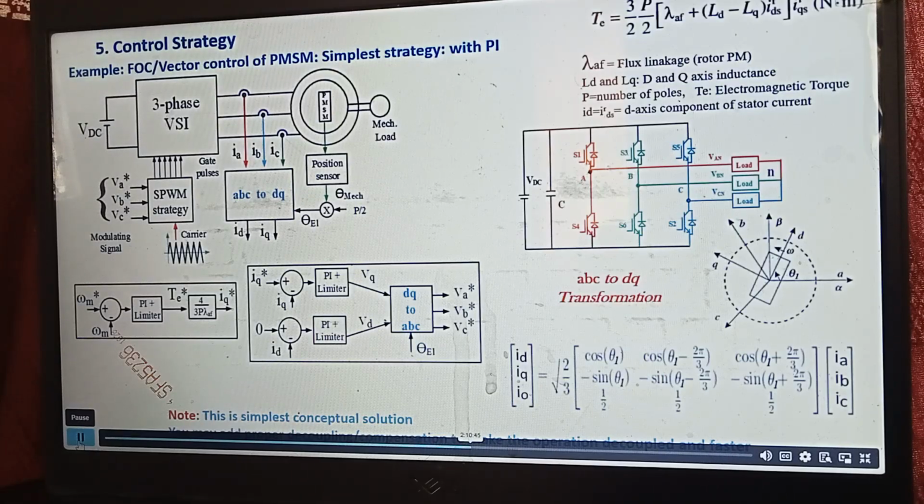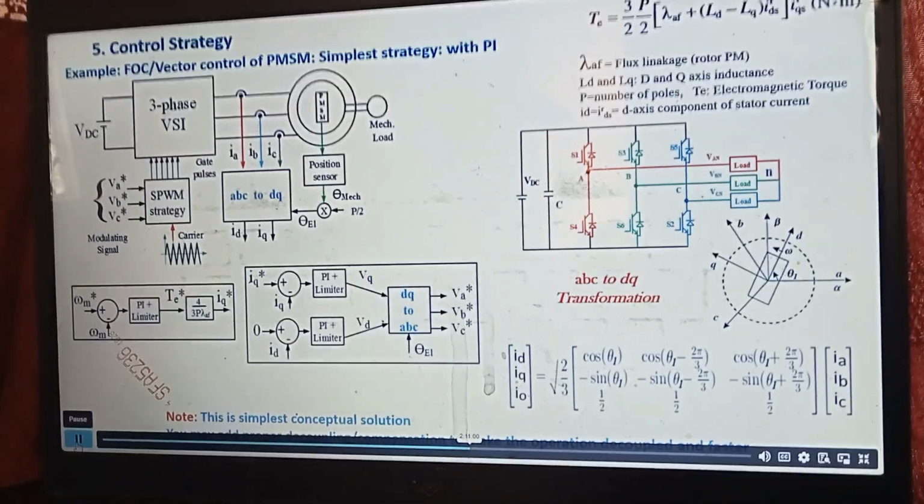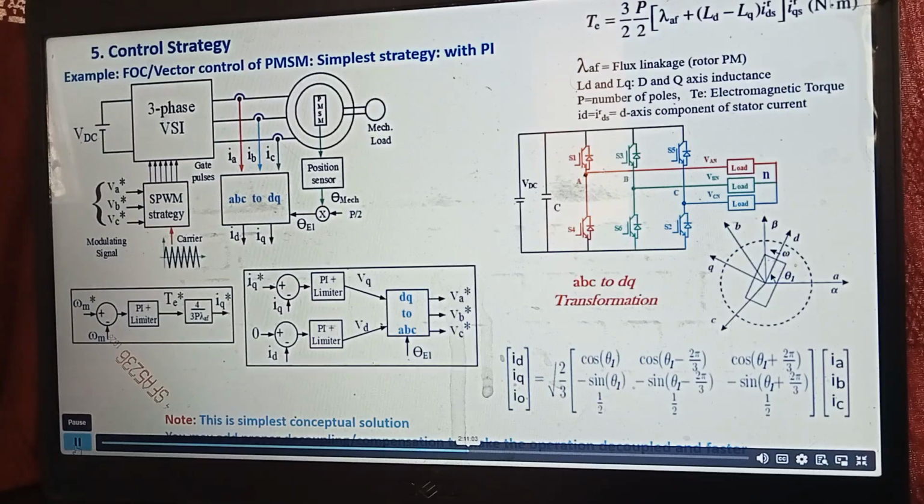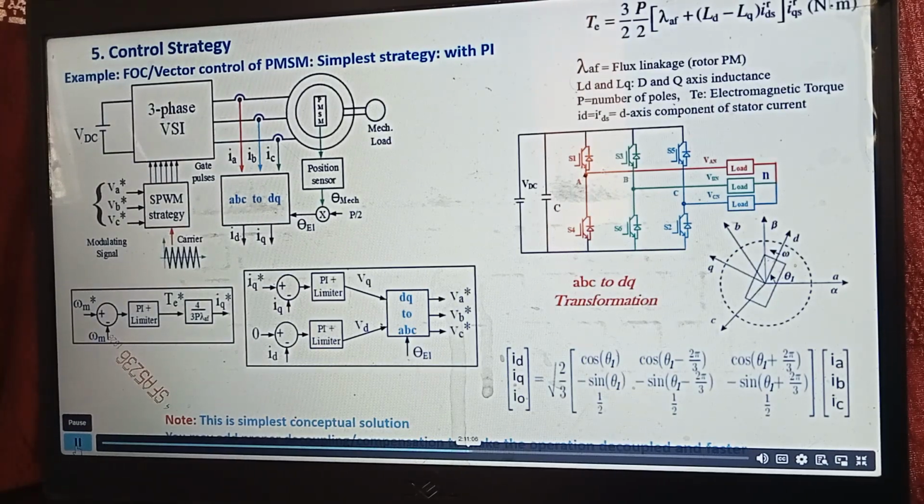Parallelly, we also decide about the control strategy, right? Ultimately, to control the motor controller, you need to know which motor you are using, and what kind of speed control strategy you have to use. For example, in PMSM, which strategy are you going to use? Field-oriented control, right? That we discussed. So all this you have to decide: I'm using BLDC, I'll go with this control. I'm using an induction machine, I'll go with that control. I'm using SRM, it will be a separate control altogether.